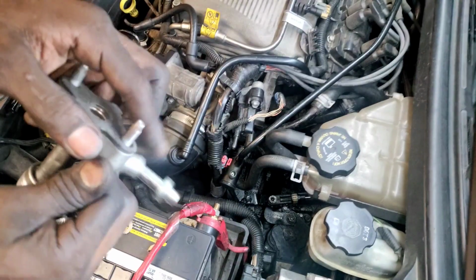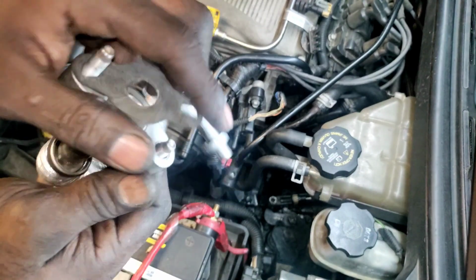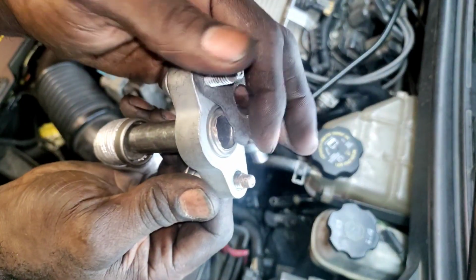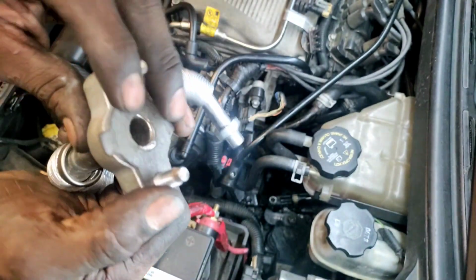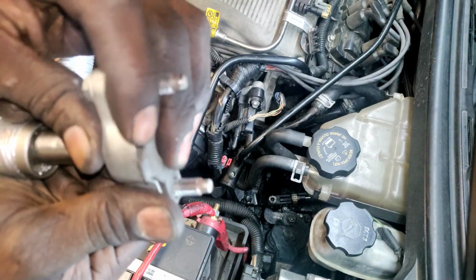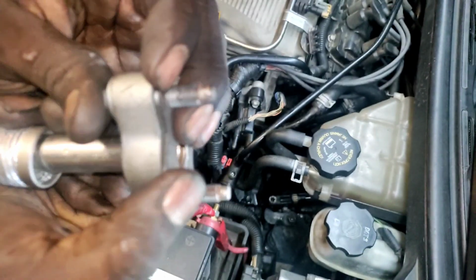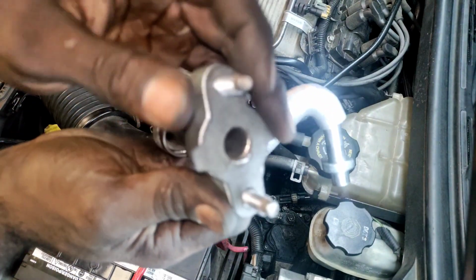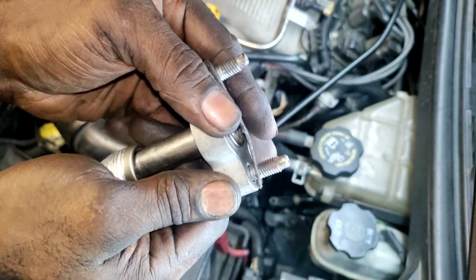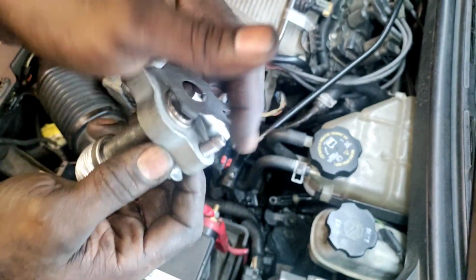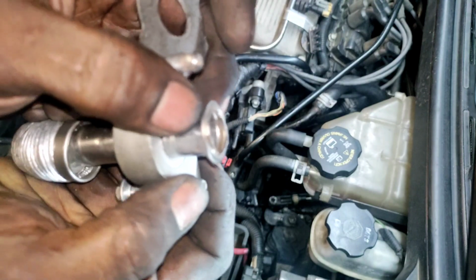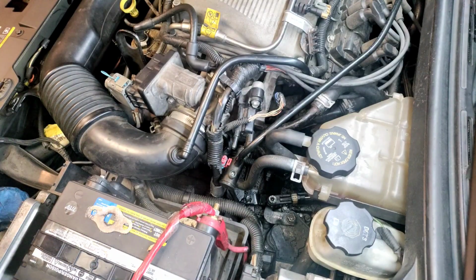Here's the game plan. I wound up putting the EGR tube on there without the gasket, got it to smash down. I took a grinder and went around it, so it's kind of flat, and it's going to serve its purpose. I didn't want to make it too terribly flat. So when I put it on there, it's going to impress the rim of that gasket, and it should seat properly. So this flange and this gasket should mate just fine with that outer rim of the EGR tube. So I think we're in good shape. Then I'll do what I need to do to get it on there.